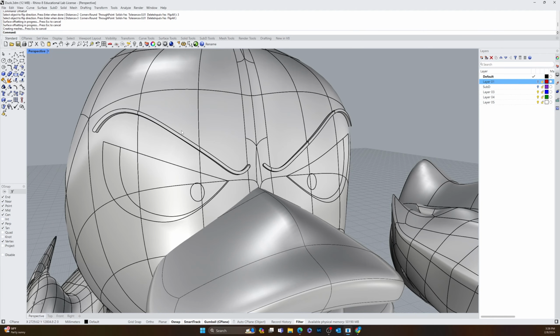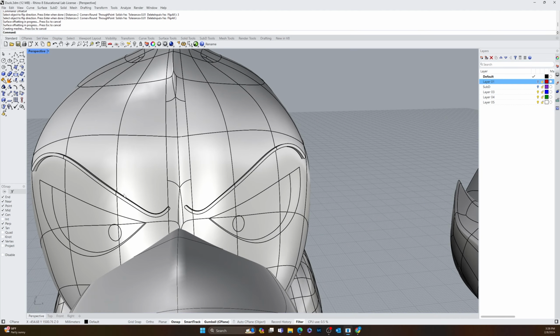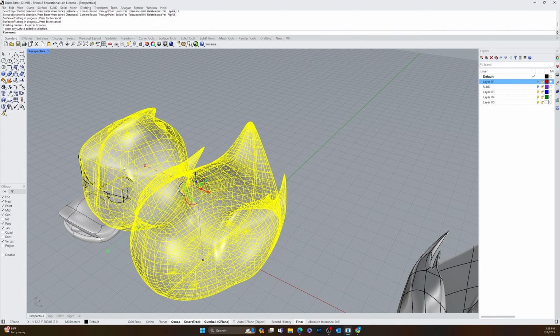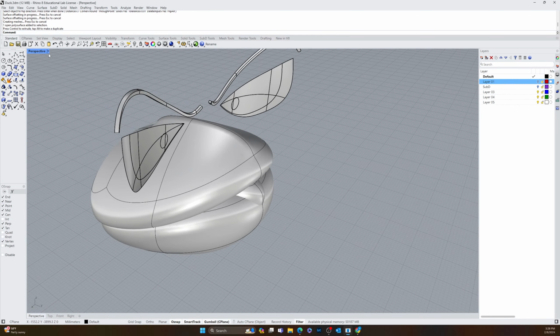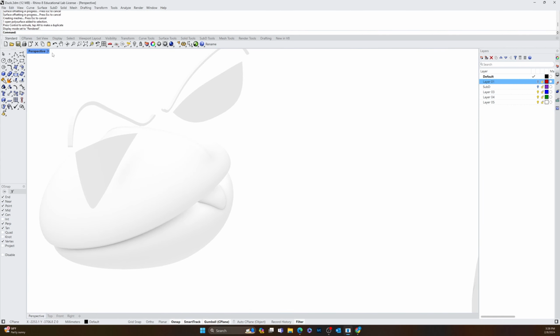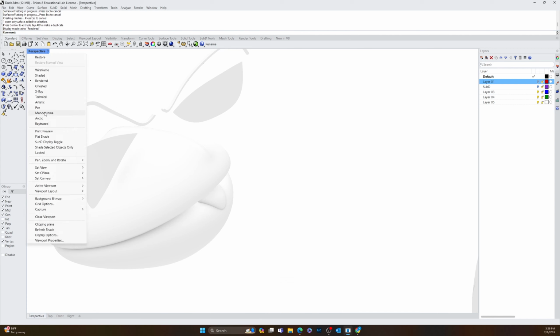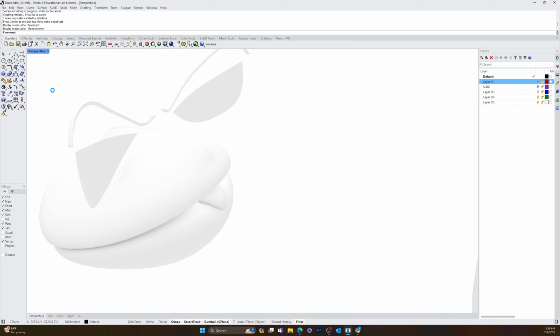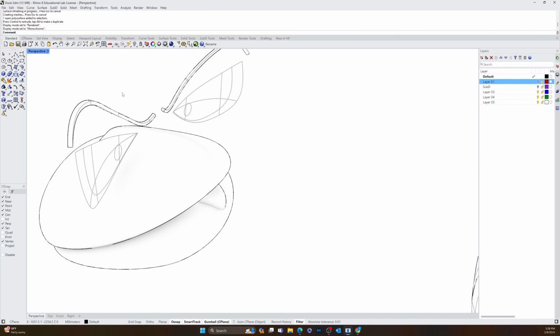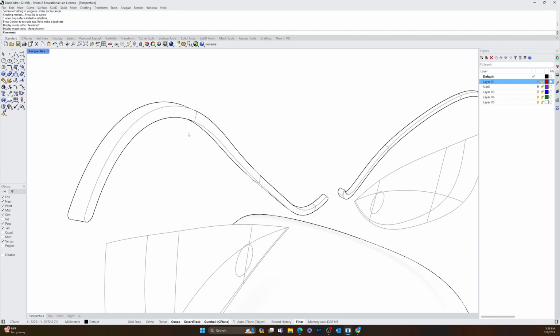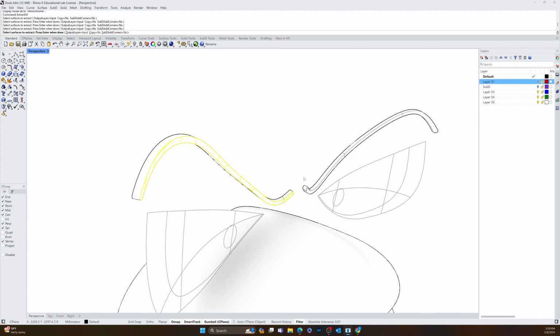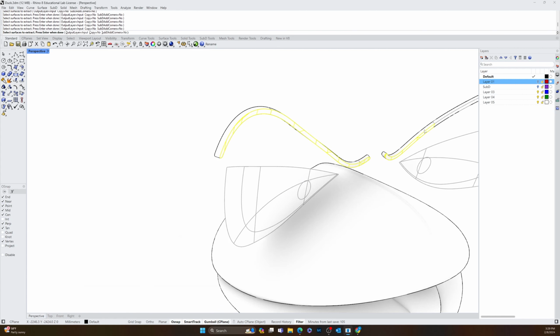Great. So now we want to make this thing watertight. It's easier to explain with the eyebrows than it is with the eyes when we get into that. So basically, if I look at this thing, move it back here, you can see that there's holes right there. And you can also see that this has a back on the objects here. Let's look at it in monochrome. First time you change it into monochrome, it always takes a bit. So it'll show you all of the edges. So this has a back to it. That does not. That's hollow on the inside. So we need to actually go through and extract these surfaces off the back of the object here and delete them so that we can create an edge-to-edge connection between this and the rest of the body.